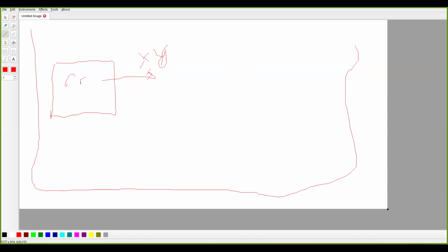And we need to generate RGB. So the controller generates the current X and Y, using counters and signals. Basically, the controller generates counters for the current position on the screen. As a module, it should have inputs and outputs. The output is X and Y, and the input is the clock and reset.